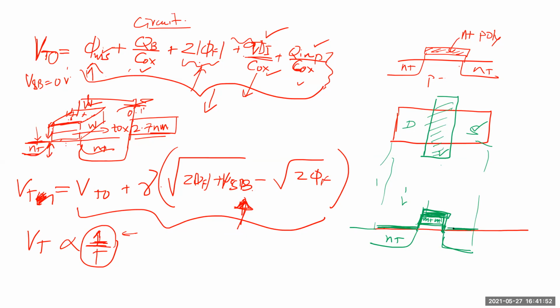So it's because of self-alignment, right? You are using poly as the mask to avoid N plus being diffused into the channel area, but it itself gets bombarded with that, and that's why you get N plus and P plus. So is everyone convinced about that? Yes or no?